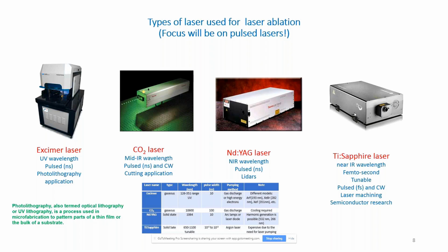It is also used in LiDAR systems. It is a pulse laser, nanosecond pulse width. Its wavelength is in near IR at 1064 nanometers. Now, the medium of operation here is a crystal, a YAG crystal, yttrium aluminum garnet crystal, and it's doped with neodymium.